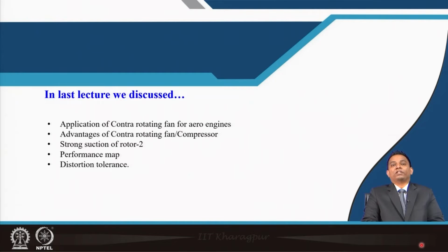Now, under that condition, the flow entering my engine will have inflow distortion because of inflow boundary layer development. That will lead to deterioration of the performance of my engine. So, people are looking for special applications or special kinds of designs where they can avoid or minimize the effect of this distortion.